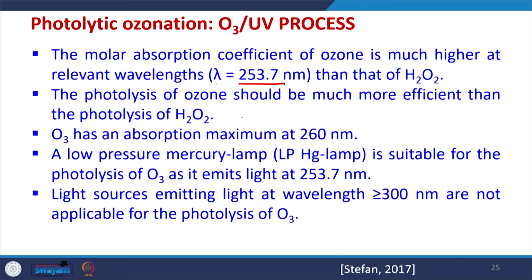This is the reason that O3 in combination with UV can be a highly beneficial as well as highly efficient process for wastewater treatment. O3 has an absorption maximum at 260 nanometers, and the wavelength for usual pathogen destruction is 253.7, so the difference is not much.